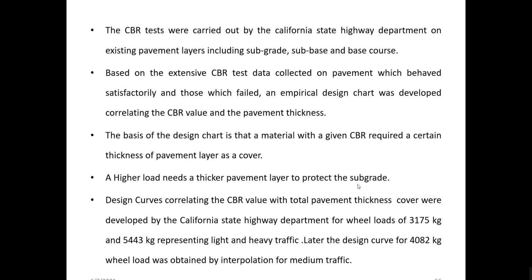We know that the subgrade is very weak in load bearing capacity. Okay, hence you are trying to construct the pavement layers above the subgrade, in the form of different types of layers like subbase, base course, and surface layer. Okay, and you also know the inferiority and superiority of the different types of materials. The superior quality material is going to be laid at the top, and inferior quality material you can expect to see at the subbase as well as the subgrade.